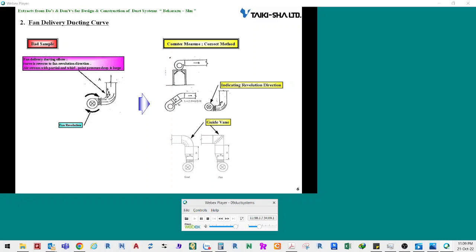If the cross-section area of the duct is extended so that 1 pascal per meter of pressure loss can be attained, guide vanes are not required, because the wind velocity is 10 meters per second or slower. You should, however, confirm whether they are necessary or not. If you design the cross-section area of the duct to be extended so that 1 pascal per meter of pressure loss can be attained, you can solve problems regarding the wind velocity.